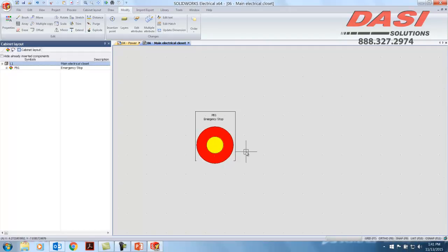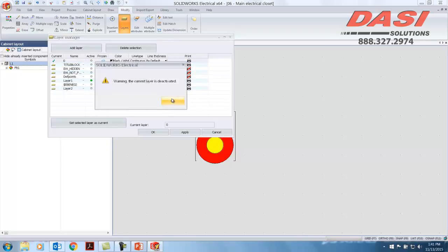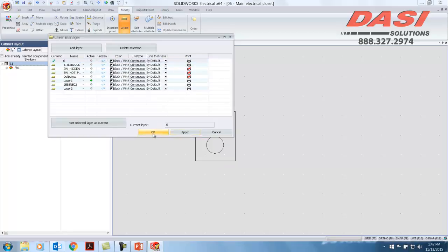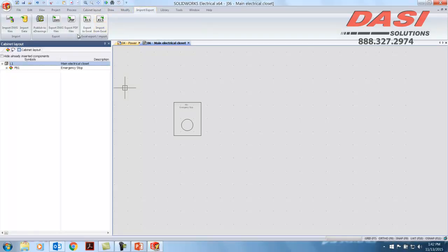All right, now that I've updated this symbol here, if you are creating this drawing, what you have available in the layers is making them active or not, and also printable. So if I were to turn these layers off, then what you should end up seeing is only the Lamicoid tag. So now, of course, if I have a full set of Lamicoid tags on a door, I can then simply go ahead and export that DWG.